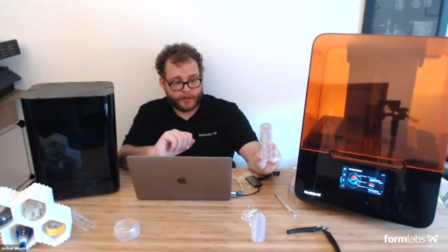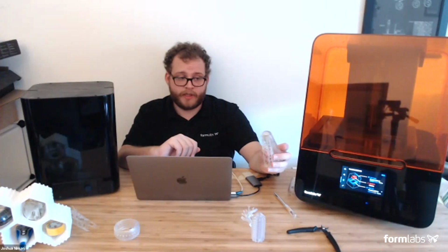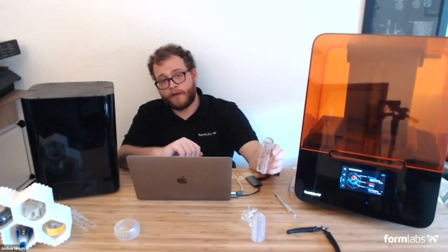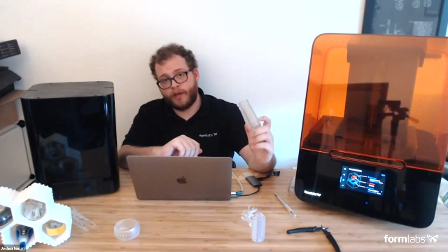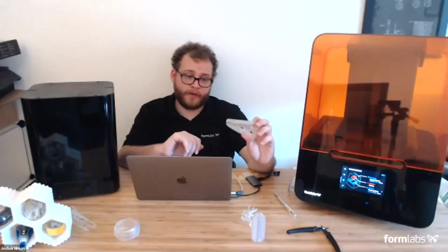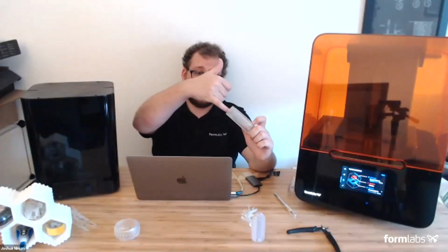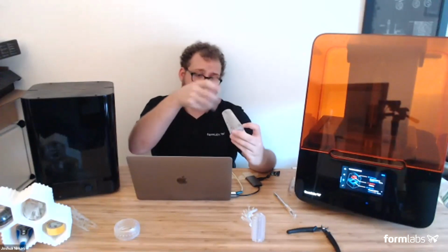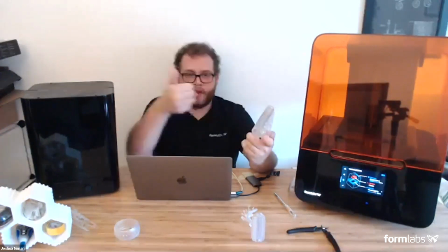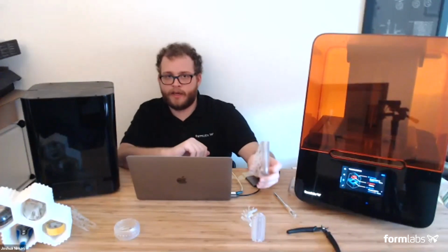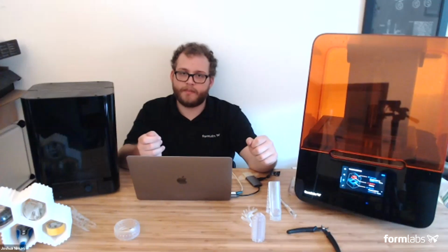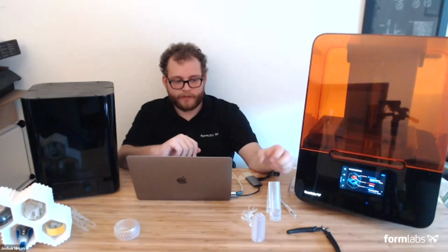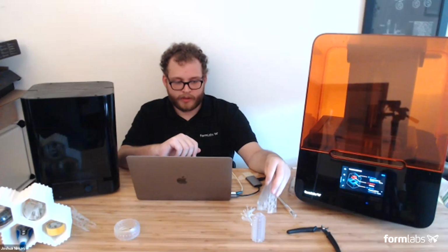One of our material product managers, Kathy, who you may have seen give a couple presentations recently, also did a lot of painting on this material before we released it because she wanted to see how it would show up. She found that for things like this, where you have an inside area, a cavity that you can reach, painting the inside of it, the color will actually show through and it looks really nice. And it's a more durable finish because it's not actually on the exterior, you're just getting that color shining through it. But it's paintable like all of our resins. Again, no alcohol-based paints, but a variety of others will work.